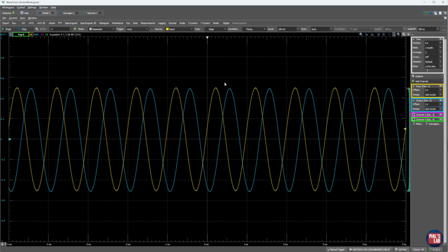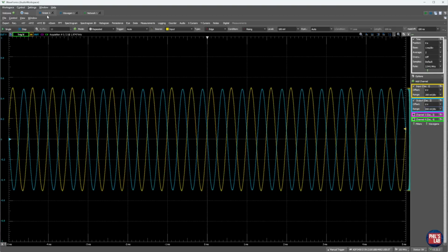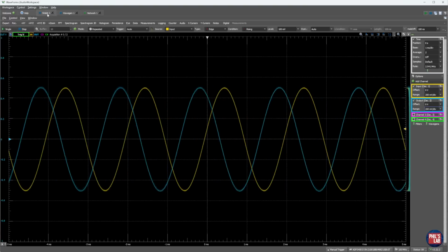Now the effect is engaged, and what we've got is this additional phase shift compared to the effect not being engaged. The magnitude hasn't changed, we've only changed the phase shift. The amount of phase delay is dependent on the frequency domain performance we saw previously. So because I'm running at 1 kilohertz, I'm going to have a specific phase delay at that frequency. If I adjust the frequency, let's say to 2 kilohertz, I'm going to have a different phase shift than before. Or if I adjust the frequency down to 500 hertz, that's going to be a different phase shift as well. And you can imagine your signal that goes into your guitar effects pedal is of course a sum of these different sinusoidal frequencies, so there's going to be a different phase shift for all of those frequencies.